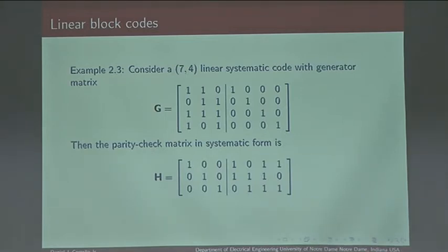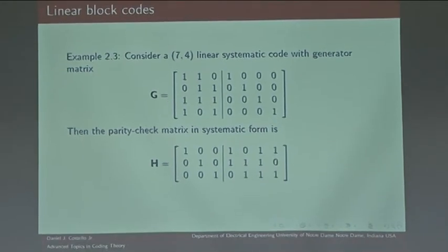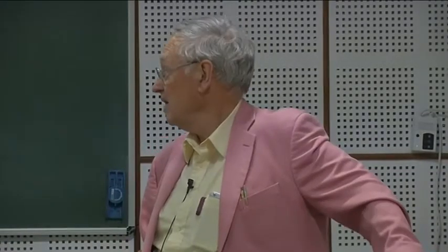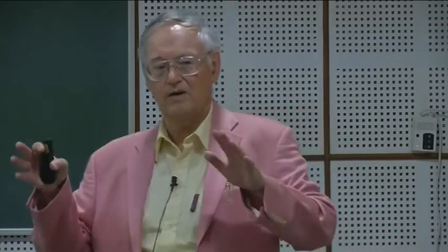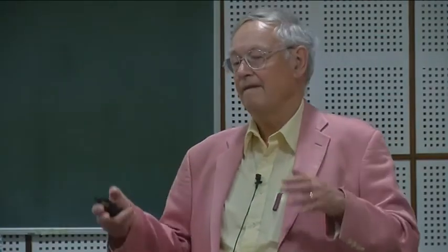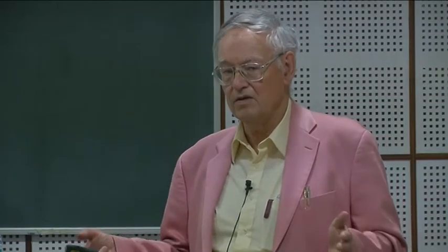So I said earlier with low density parity check codes, this can sometimes be a problem. Why is it a problem? Well, because low density parity check matrices are not defined in systematic form. Actually, systematic form would be a bad code. A parity check matrix which had a systematic part would perform poorly. So low density parity check codes typically are non-systematic.